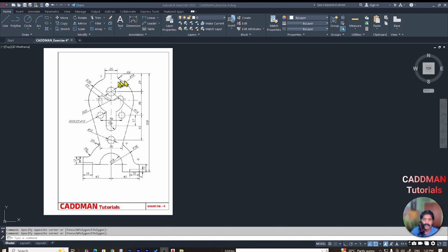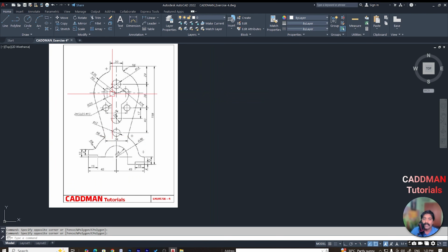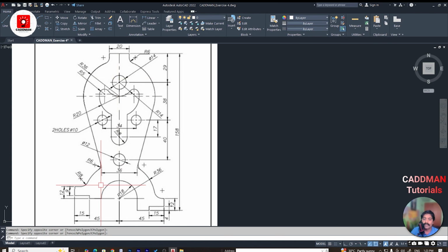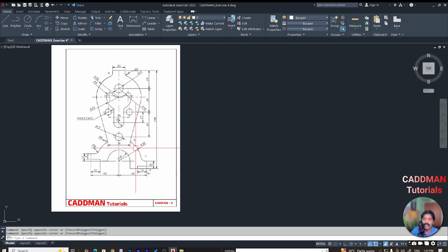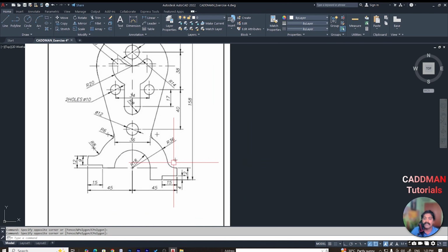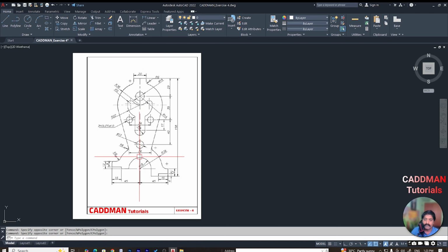Today we are going to create this drawing in AutoCAD. So let's get started. Before creating any drawing, first you need to look out for the references so that you can build the drawing one by one. Here I take this center line and this center line as a reference and start building this profile first, and then offset this line to a distance of 158 to get this 120 dimension line, and then keep on building with the references given from the top line as 29, 38 and 44, these reference holes. So let's get started.